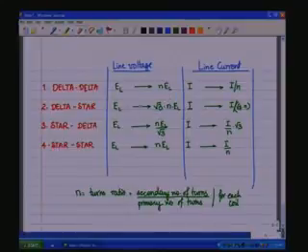So, in the case of the delta star, the insulation breakdown specification is 1 by root 3 lesser than in the case of the delta for the same primary secondary voltages, because here the secondary phase coil and the primary phase coil are seeing a difference of n times EL, whereas here for the same secondary voltage, the primary and the secondary phase coils are seeing n by root 3 as the voltage difference between the phase coils.